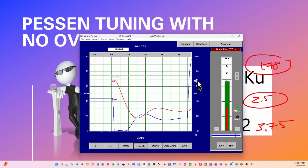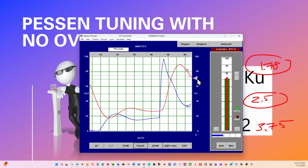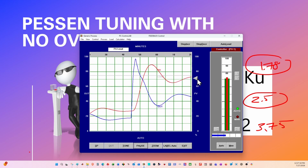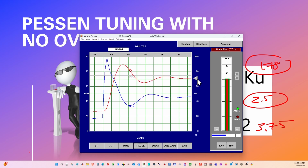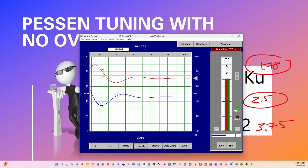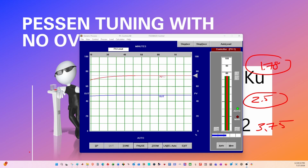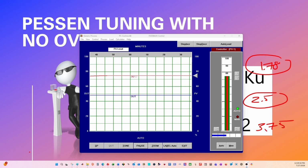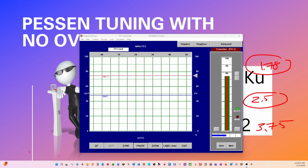I'm just going to take that value up, and if you can see, there is going to be a certain amount of overshoot. Now, this is where something that I said a little bit earlier comes in: the fine tuning needs to come in, and you might just want to change it because, of course, we don't want to have any overshoot whatsoever. So once you've got a base value to work from, you can fine-tune that base value. In my case, I do believe that the gain value is too high, so I'm going to reduce that substantially. I've just taken my gain value and divided it by 8. And at the same time, I've doubled my integral value.